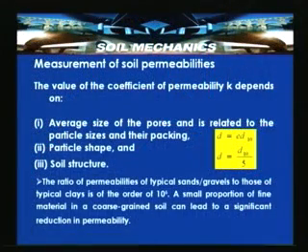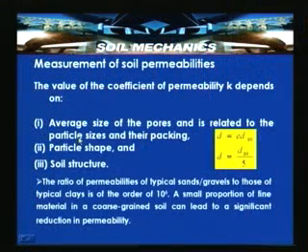So, measurement of the soil permeabilities. This particular slide we have already seen. Let us look once again into this particular slide. The value of the coefficient of permeability K depends upon the average size of the pores and is related to particle sizes and their packing. So, larger particles can have larger pore spaces and smaller particles can have smaller pore spaces. It is also related to particle shape, it can be angular or subangular or rounded.